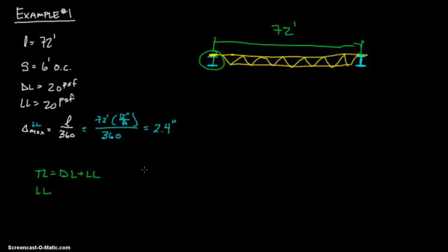So let's figure out what our loads are. We already know that the dead load is 20 and the live load is 20 PSF, but in this case we're looking for pounds per linear foot, PLF.